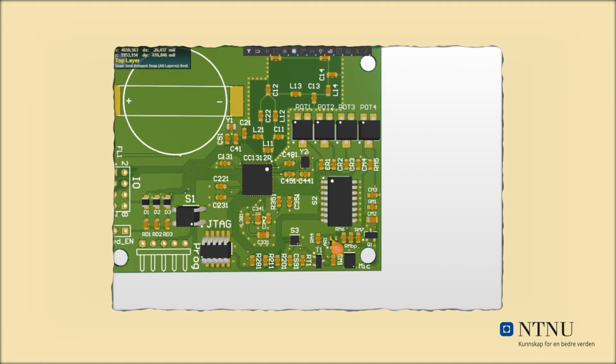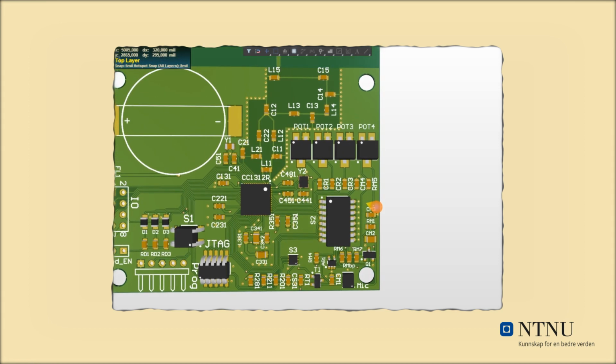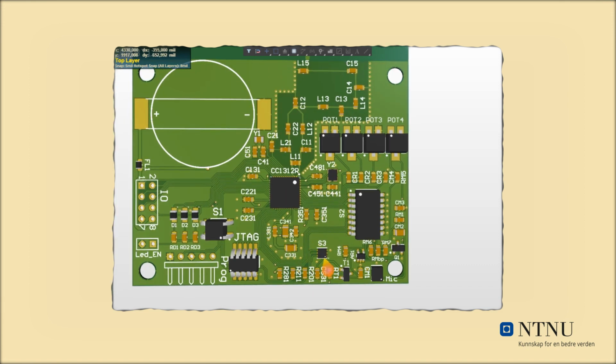We also have a dB sensor here. It consists of a mic, an op-amp and some filters, and an inverting circuit, which you don't have to install. It also has a bypass resistor here. It also has an adjustable gain set by this potentiometer here, which is part of the calibration potentiometers, which we use for both the temperature sensor and brightness sensor, and a threshold for noise.